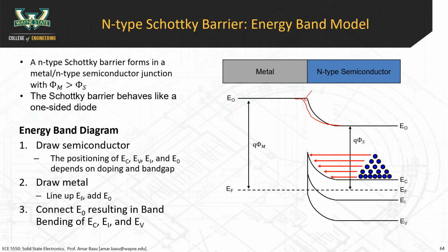So this is behaving very much like a one-sided junction diode. All right, so you have your built-in potential here, qV0, and then you also have this thing which is different from a diode. You have this thing called a barrier height. The barrier height is the distance between the height of this barrier compared to the Fermi level on the metal side. Okay, and just from this diagram, you can quickly see that the barrier height is equal to qV0 plus EC minus EF.